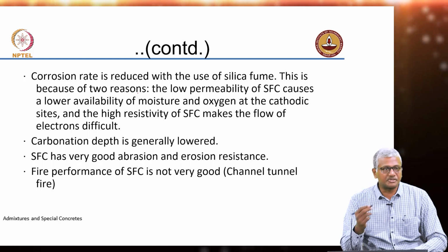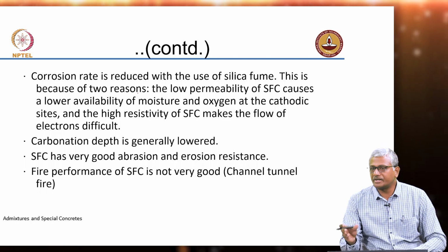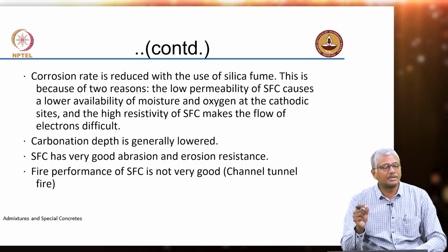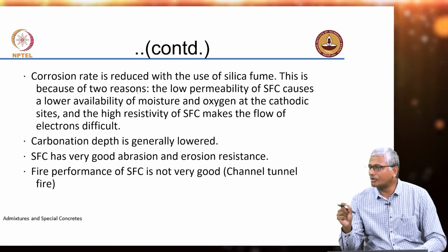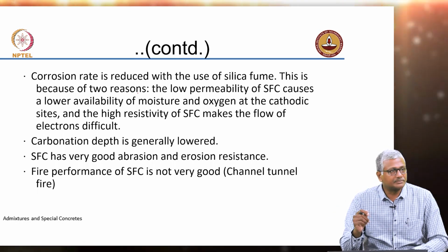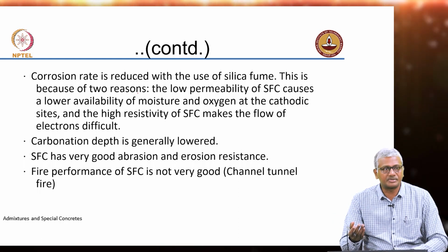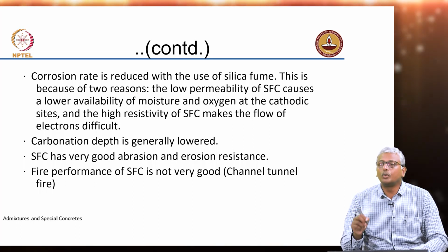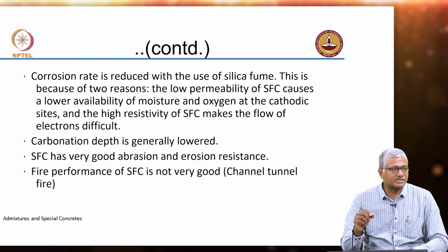The issue is, when you substitute cement with mineral additives, we know that we are converting calcium hydroxide into CSH. So, in carbonation of blended cementitious systems, you have very little calcium hydroxide available to offer some initial resistance to the passage of carbon dioxide. So, your CO2 will be able to penetrate greater depths in blended cementitious systems, irrespective of the fact that blended cements have lower permeability as compared to concrete with ordinary Portland cement, right.